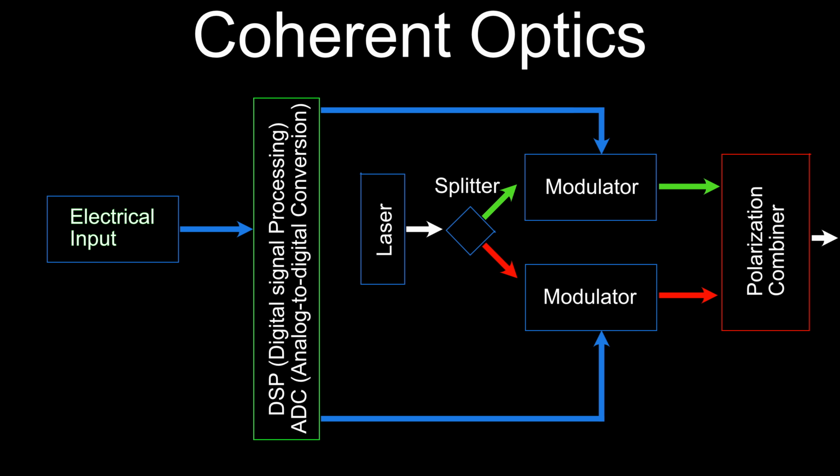That light is then split and sent into 2 modulators that use some amazing techniques to encode the bit stream onto them. Then they are recombined into a phase-shifted version of the same wavelength. This not only allows for more data, but if the waves are combined properly in just the right phase, they can actually support one another and increase the transmission distance.